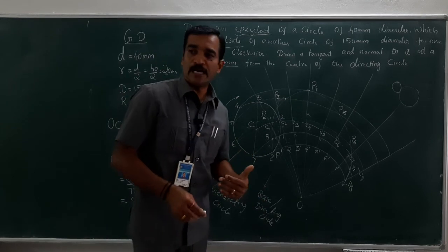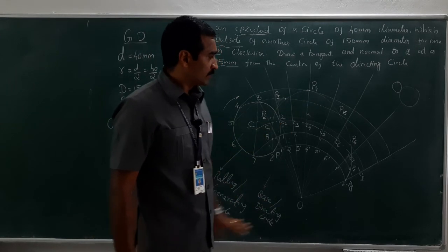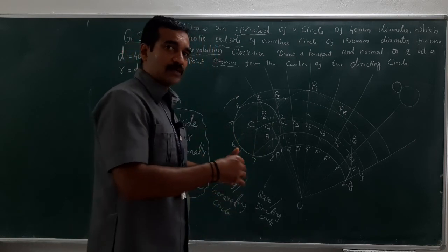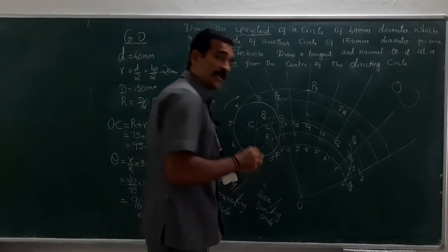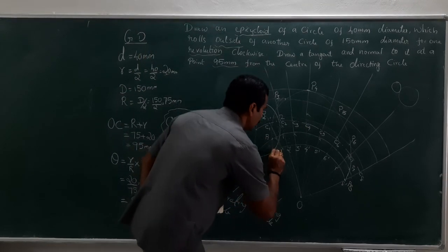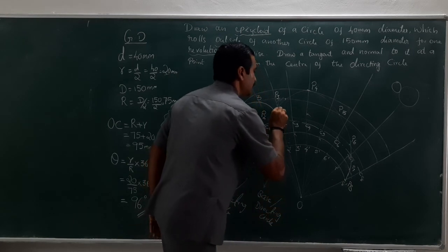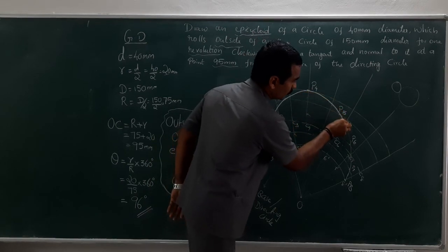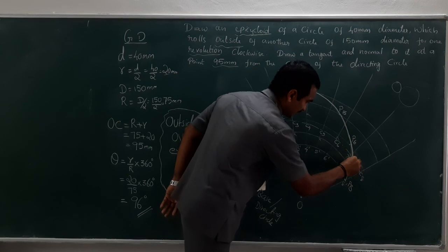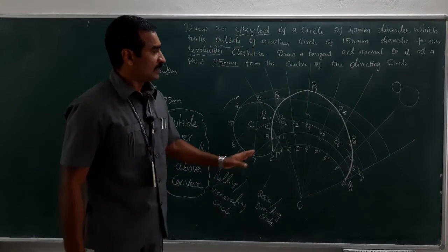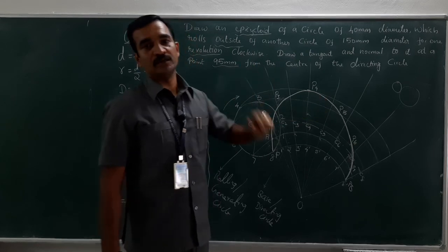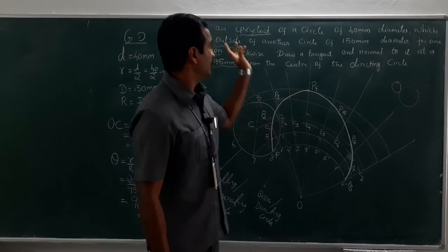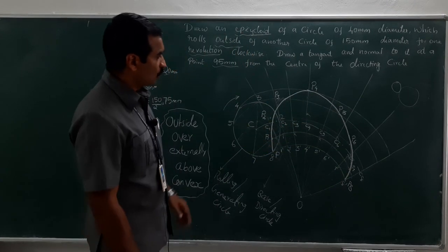Once you are confident enough that this particular curve has been constructed as a smooth curve, then you can change the pencil to HB or H. Then with free hand you just draw the curve over the thin curve which you have constructed. Right. This is nothing but the epicycloid curve. So I have completed the construction of this epicycloid curve. Right. Now, what is left?